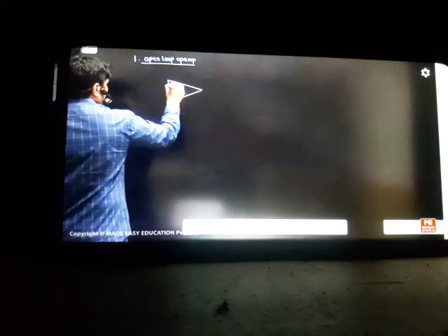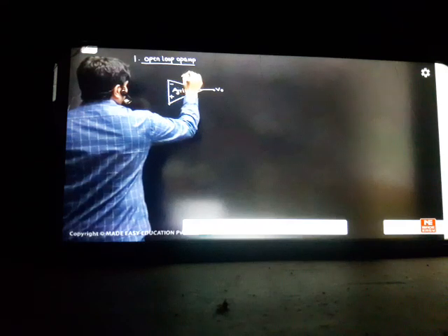Nicely understand the concepts. Suppose I have taken an example to study like this. This is an example I am taking. Minus, plus. The AD inside, suppose, is 10 power 6 that I have taken. 10 power 6 means high gain. Op-amps will have high gain, around 10 power 6 is the practical value I have taken. This is your output. And the positive battery here we can call plus V sat from now onwards.